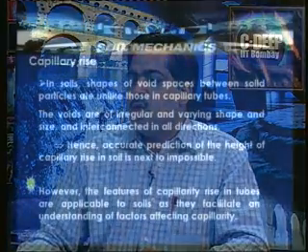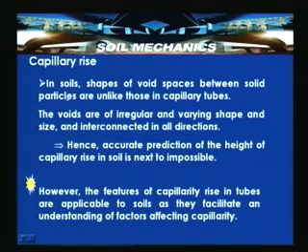In soils, the shapes of void spaces between solid particles are unlike those in capillary tubes. Definitely, the pore spaces or void spaces are not as regular as capillary tubes. The voids are of irregular and varying shapes and sizes, and are interconnected in all directions. Hence, accurate prediction of the height of capillary rise in soil is next to impossible.